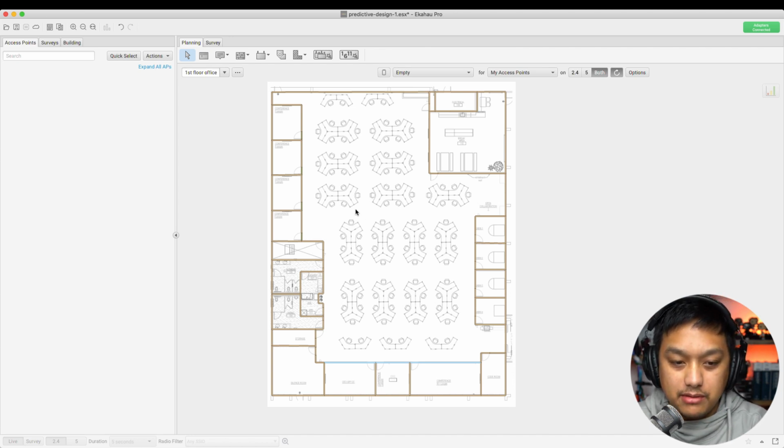All right. So for the wall, what I usually do, if I go on site and measure the attenuation of the walls, that's what I would use. If I didn't get to go on site, what I would tend to do is estimate the attenuation of the wall. So if I know they have drywall, instead of using 3 dB, I would use like 5 dB, for instance, just to overestimate the attenuation when I do the design, just to make sure I don't run into bad surprises when I do the validation if I don't get to go on site.